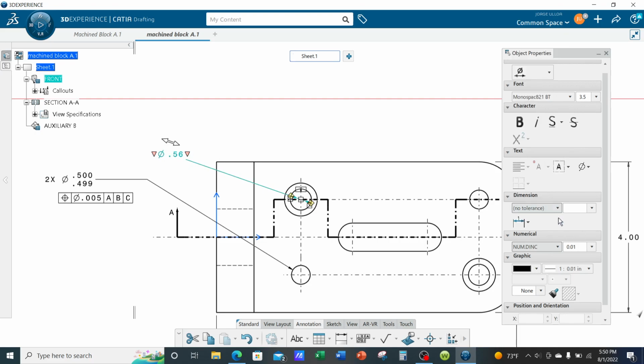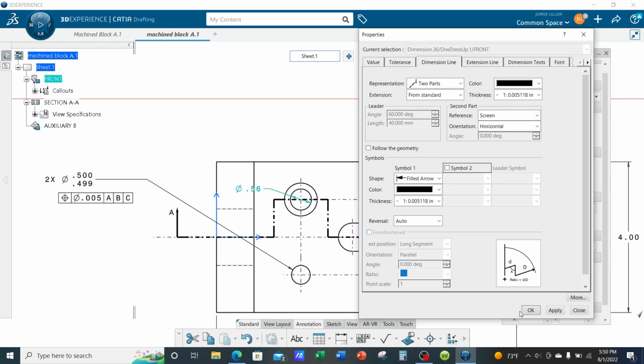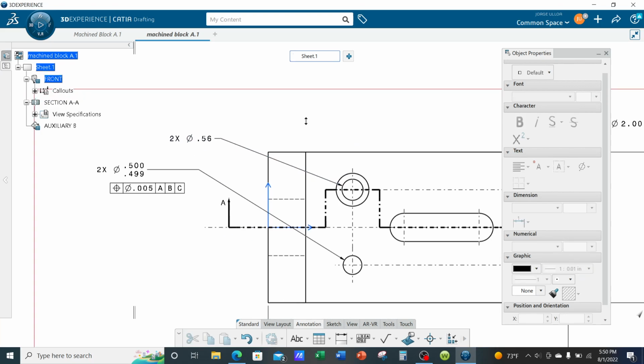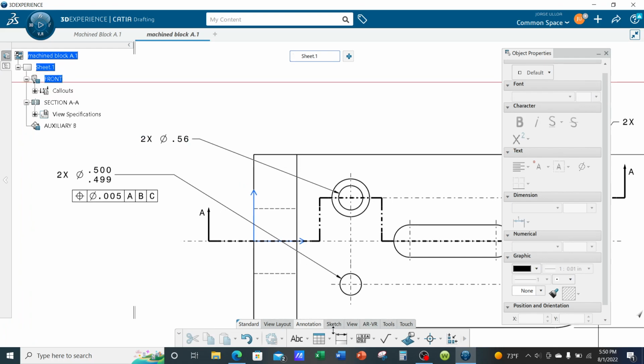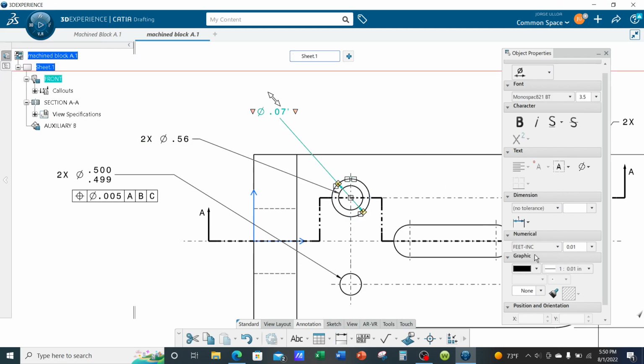Let's add the handle or extension. And let's remove the second arrowhead. Right click properties. Remove second arrowhead. OK. And let's add the 2x. Quantity of 2. There's 2 counterbore holes. Okay, now our large diameter hole is 0.88. Actually, we may need to go a little bit with the larger diameter, but I'll just leave it the way it is to provide clearance for the head of the bolt.